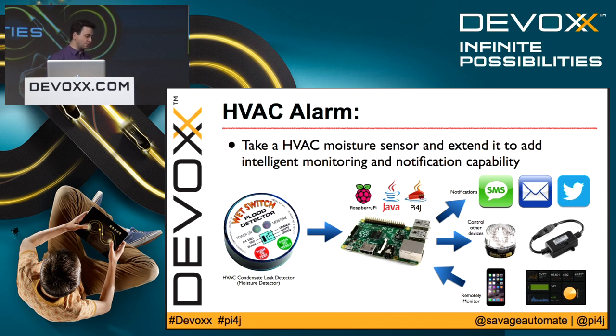Next, HVAC systems. When the air conditioning's running, they collect condensate water. When they're working properly, they dispose of that condensate water through safe sewage systems. However, oftentimes in the States, we have HVAC systems installed in attics, which is a very dirty place. Insulation, insects, and things like that get into the pipes and clog the condensate drain. When that happens, the condensate overflows and goes into a catch basin. So there's an overflow catch basin beneath the HVAC unit.